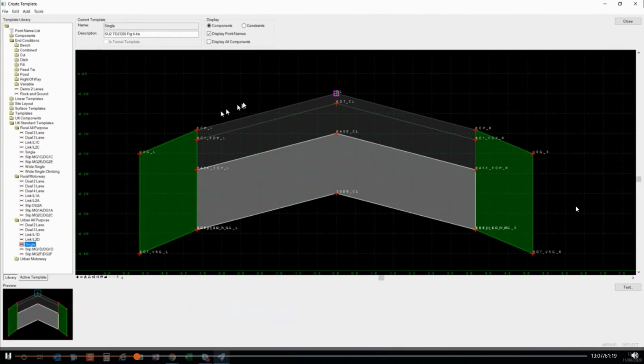So as you may be aware, a template is based on 2 elements. So you have your components, that will be the shapes between the different points, and the points. And then these elements can be just simple layers like this for instance, your pavement, your verge, or anything, or end condition, as Simon will show you.